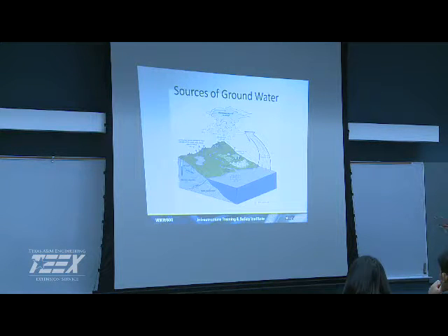All right? We're also going to have surface runoff, but we have two different types of aquifers that we're looking at. We have the shallow water table aquifer that's unconfined, so the actual water level moves up and down as you're pumping out of it. Most of those are alluvial in nature. What are alluvial aquifers? They're aquifers that are close to rivers in flood zones. As it floods, it pushes out a lot of silts and rocks, and over time it builds up, and that's a great storage opportunity for water.